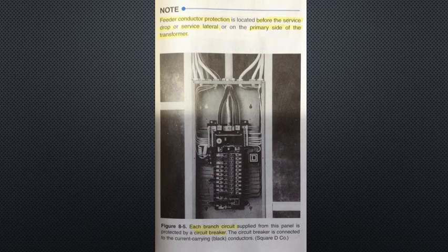In circuits exceeding 800 amps, the required size or the next lower standard size of overcurrent protection must be used. Overcurrent device location. The concise rules for locating overcurrent devices, both within the circuits and on the premises, are stated in sections 240.15, 240.21, and 240.24 of the code.